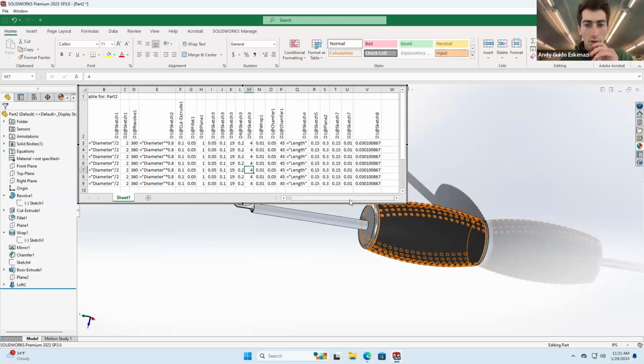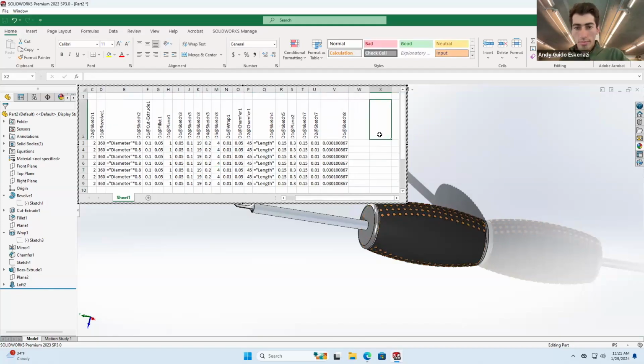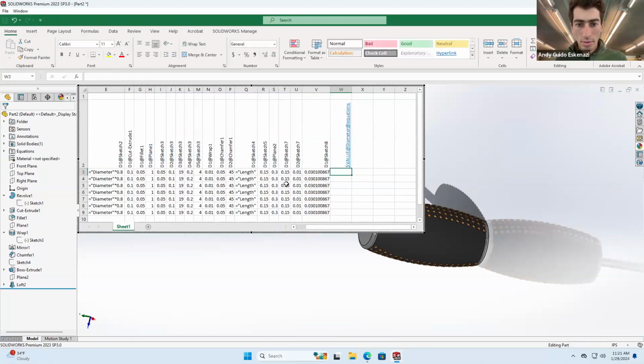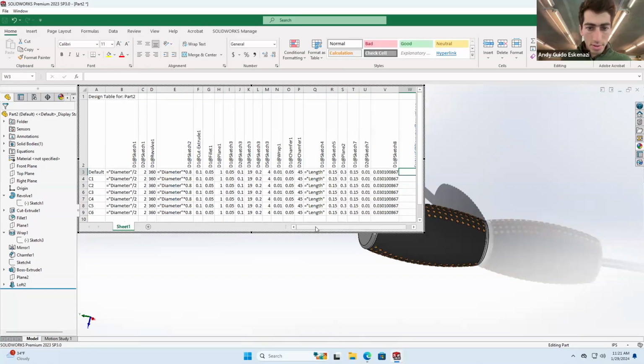And then just as usual, I'm gonna go to my very last column and I'm gonna type again $, value, or value in capital letters, at, so what were our equations? One of them was diameter. Add equations, good. Then the other one was length.